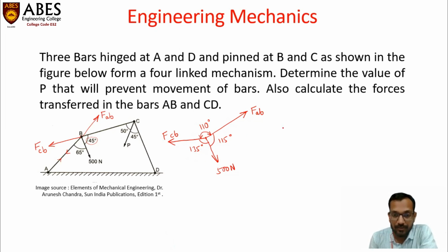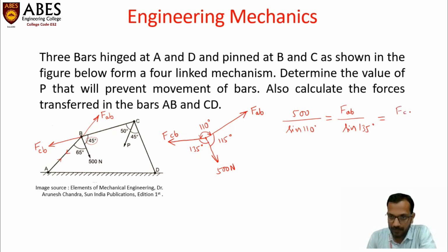So let's apply Lami's theorem. 500 upon sine 110 degrees is equal to FAB upon sine of this angle, 135 degrees, is equal to FCB upon sine 115 degrees.